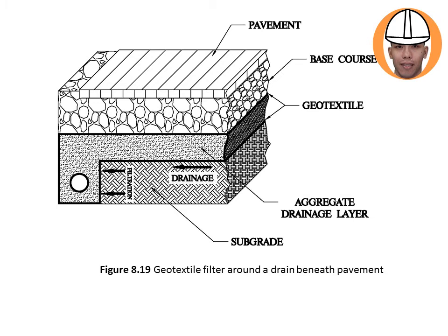For the filter, you don't want the bigger particles to go into the smaller particles. So in this case, you want to separate the base course from the subgrade, so that you have a structure with high integrity.